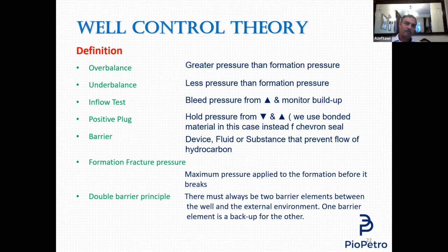But before disconnecting my equipment and leaving, what we used to do is close this swab valve, bleed off the pressure above it to zero, then close. Sit on the chair for 10 minutes watching the gauge. What I'm doing now is an inflow test on the swab valve to be sure that it is holding the pressure below it. Yes, I did the test before the job, but I have to do the test now again. But these days, once you close the swab valve, bleed off the pressure, close, inflow test it, then open, disconnect.